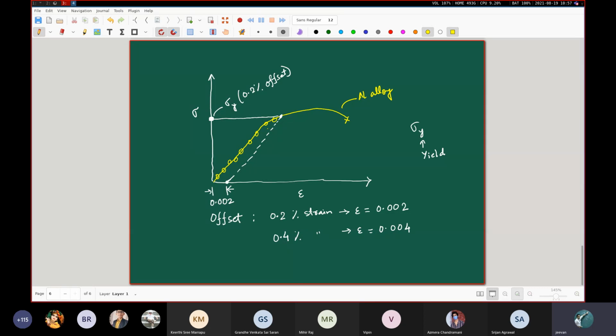And please note that these are things which are a little bit sensitive to the ambient temperature also. So there is that extra degree of control which you need to exert. I mean, an experiment carried out in Paris and an experiment carried out in Kharagpur may actually yield different values of the yield stress just because you have not accounted for the difference in temperature.